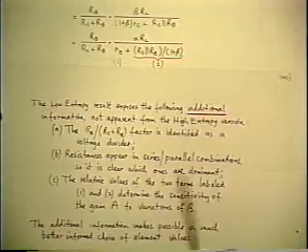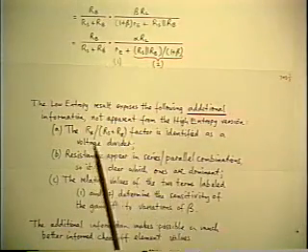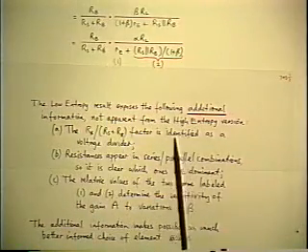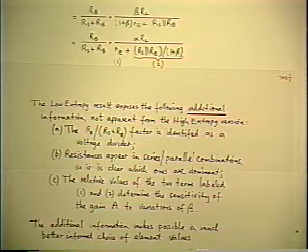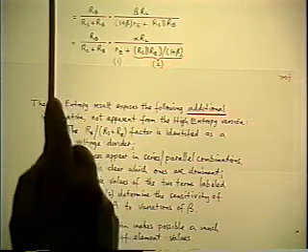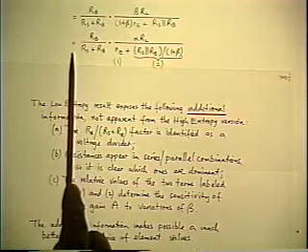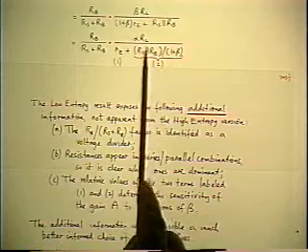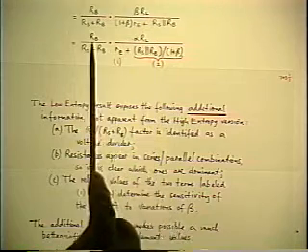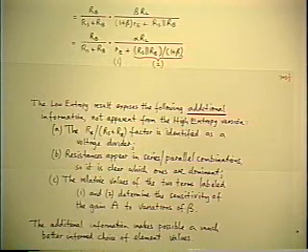First, this resistive divider factor in front is identified as the voltage divider directly from the source. We know that factor is less than 1. So whatever value of gain we have to design into the specification, we know that the second factor in the result has to be bigger than 1 sufficiently to overcome the loss of the first factor.